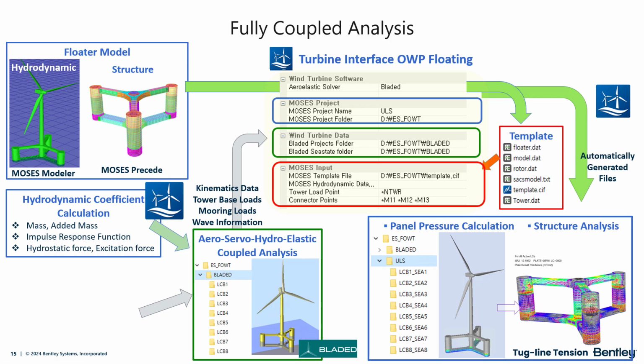Gentek also carried out a fully coupled analysis for verification purposes, using MOSES' ability to interface with Bladed, the turbine engineering tool. Here's the workflow they followed. First, they created an analytical model in MOSES. This included a panel model for hydrodynamics, and a structural model for structural analysis.